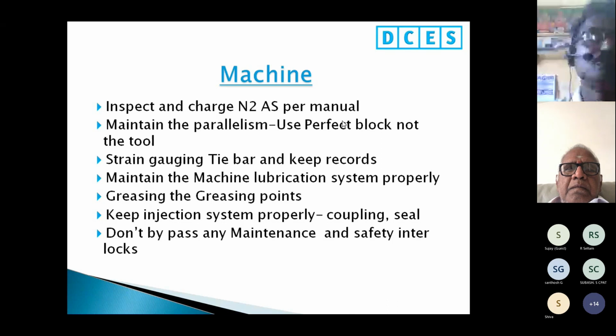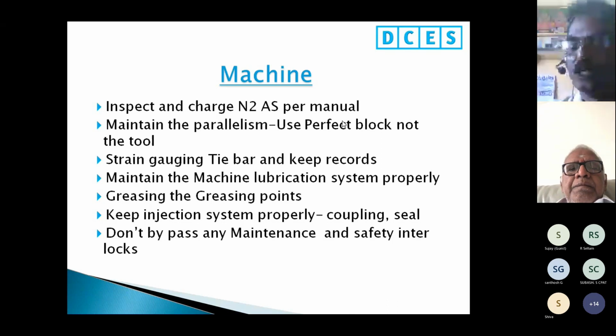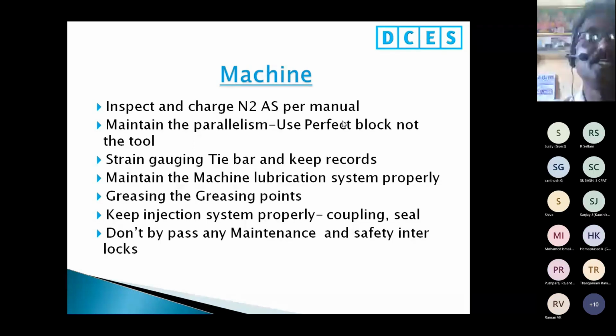This is also one of the very, very important areas, and people don't focus on this. And greasing points. Keep the injection system proper. The coupling: if the coupling has 8 screws, must use 8 screws. Sometimes if one screw is broken, it must be replaced immediately. And the seals should also be changed properly. And don't bypass any maintenance and safety interlocks.